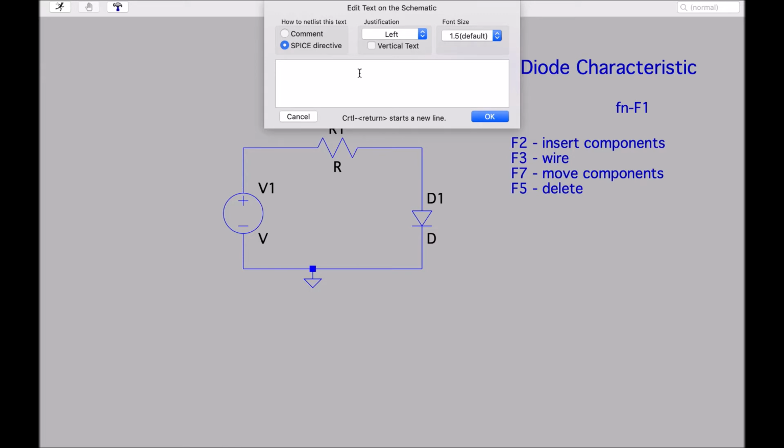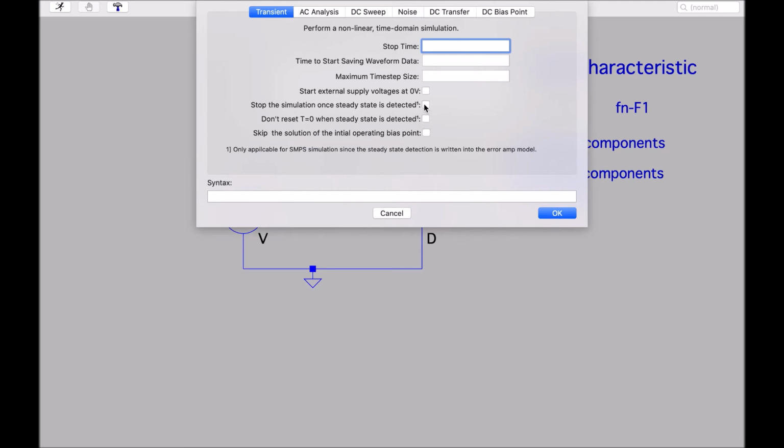Now again, on the Mac version, it's very hidden. If you're familiar with spice and spice commands, you can type directly into this box here, but hidden very sneakily away, if you right click on that box, there's this help me edit option, and in here analysis command, and we're going to choose that. It's going to help us to write our spice directive correctly.